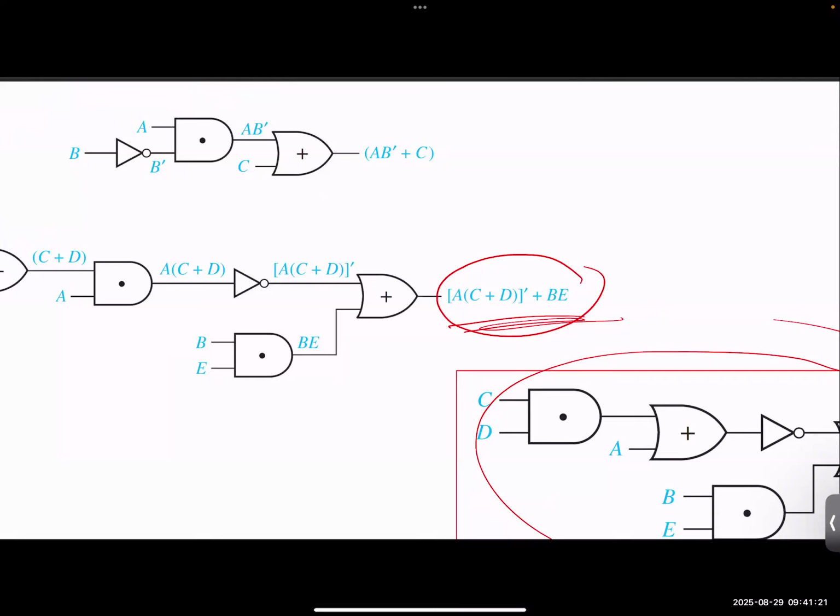So not all Boolean circuits will be giving you product of sum or sum of product. You have to work for it. Okay. Are you still with me? But can you feel that given a Boolean function, you could always reduce it down to a sum of product or product of sum? Product of sum, I told you it's more difficult to get to, but theoretically it's possible. But sum of product, you can be confident. Just multiply everything out. Don't even think about it. And then whatever the bare minimum you're left with, it's always going to be sum of product.